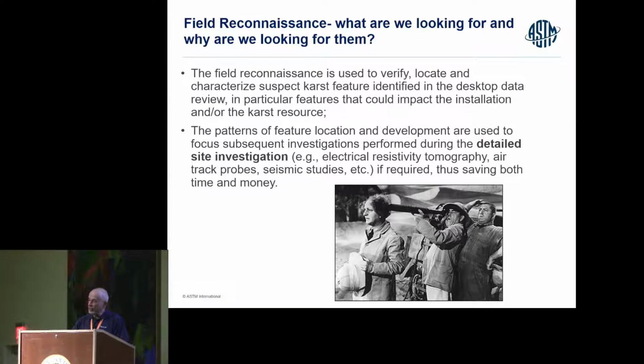Generally the detailed investigation is invoked if features that we have found during the field investigation might be impacted by the proposed development. When we say impacted by the proposed development, it could be, for instance, a sinkhole slightly off-site, impervious surface is put in, and drainage from that impervious surface would run off-site to that sinkhole, possibly causing some kind of contamination. So that's when the second phase comes in.